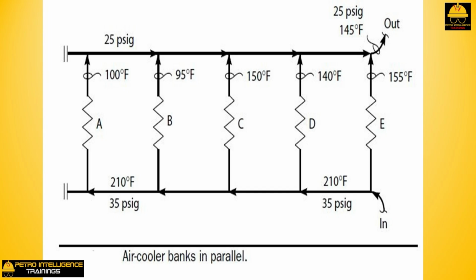11. The iron sulfide, or pyrophoric iron, accumulates as a blackish-gray deposit inside the tubes. 12. This deposit further restricts vapor flow through the low-flow tubes. 13. The reduced flow causes a lower tube outlet temperature. 14. The lower tube outlet temperature promotes higher rates of salt sublimation from vapor to a corrosive fouling solid.